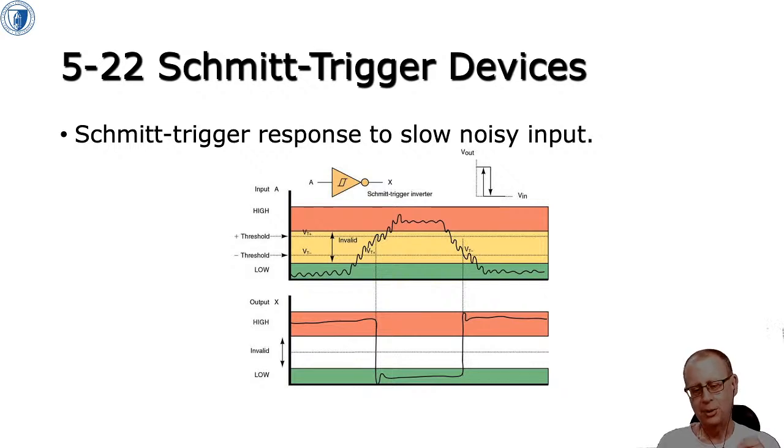That's the first piece I wanted to talk about. The next piece I wanted to get towards is circuits that generate clocks. Remember, we talked about synchronous versus asynchronous logic circuits, and a synchronous circuit has to have a basic clock that all of the inputs and outputs change on, whereas in an asynchronous circuit, all of the outputs change immediately when an input changes.